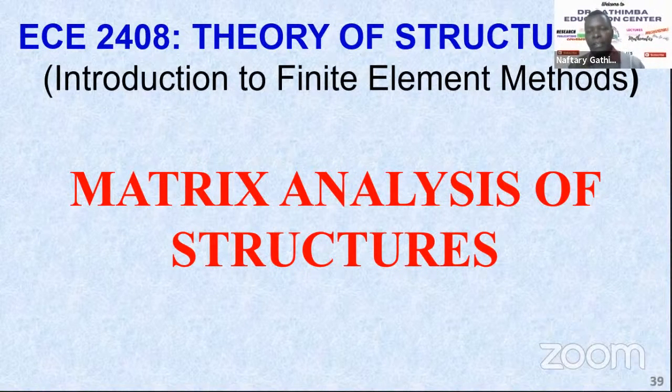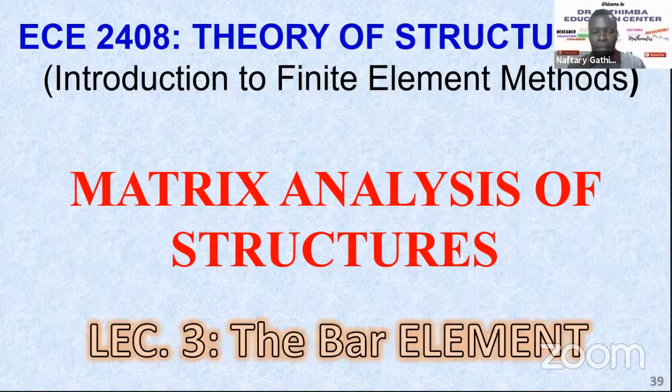We covered a simple and unique finite element called the spring element, which we said was for understanding the processes involved in formulating the equilibrium equations or finite element equations. Now, today in lecture number 3 we go to the second element that we are calling the bar element. This is an actual element that you can use in a structure. Remember, the spring element was for illustration purposes, though there are some supports that we treat as springs, but of course, in real-life construction of structures, we don't have springs.